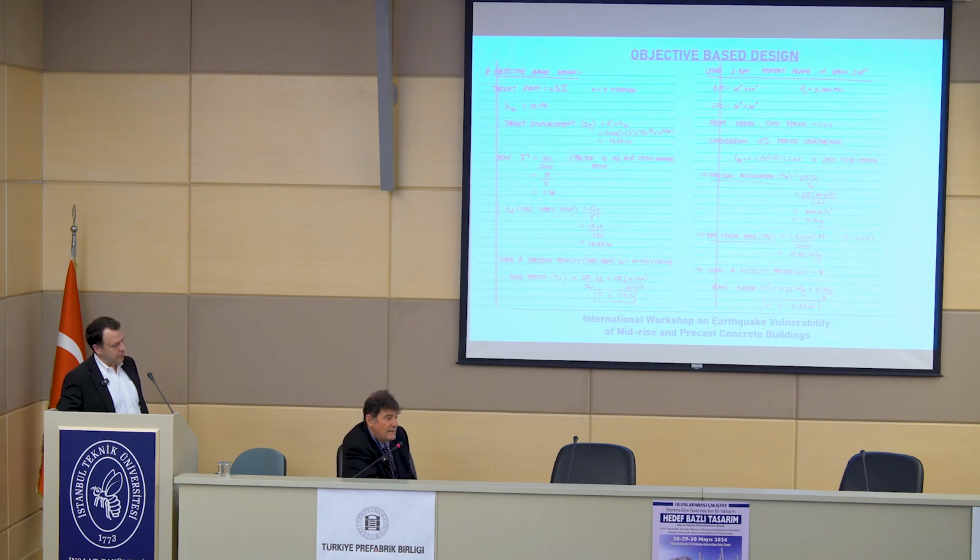Okay. Here, just like you had adopted, assuming that there is some period lengthening as you go to higher drifts, and assuming that value, then it would be closer to 1.4. But still at 1.4, we haven't really reached the 1.5 target. So you could go in and change your sections such that you would get closer to your target values.